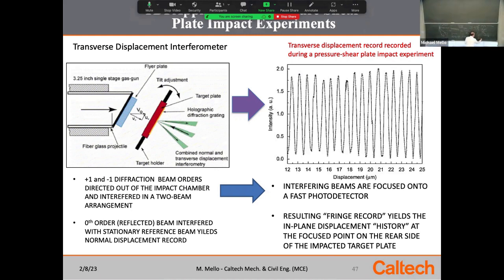Okay, so ultimately this is what everybody wants, right? They want this stress strain curve of a material, say in shear, okay? And there's no tensile testing machine in the world that could give you 10 to the 5 or 10 to the 6 per second strains, okay? Tensile testing machines like the ADMET downstairs or Instrons give you maybe the fastest ones 10 to the 1, okay, strain rates. Imagine this huge hulking device is going to have to pull so quickly.